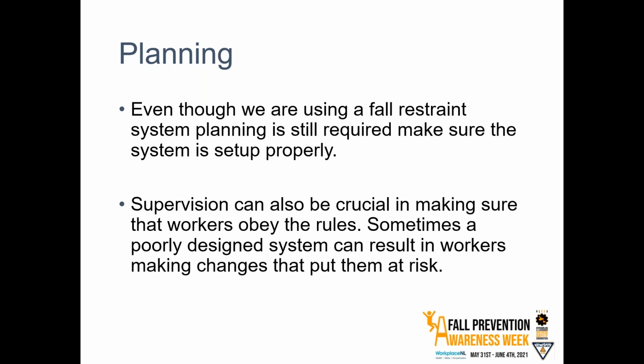Like, for example, if we are in a scenario where my fall restraint system has been set up, but I don't actually have enough lanyard length to get to my work area and do the job that I need to be doing, really I should be going back to the person who set up that plan, the supervisor ideally, and tell them that the plan is not working so that it can be adjusted. I shouldn't be coming up with ways to carry on doing the work on my own.